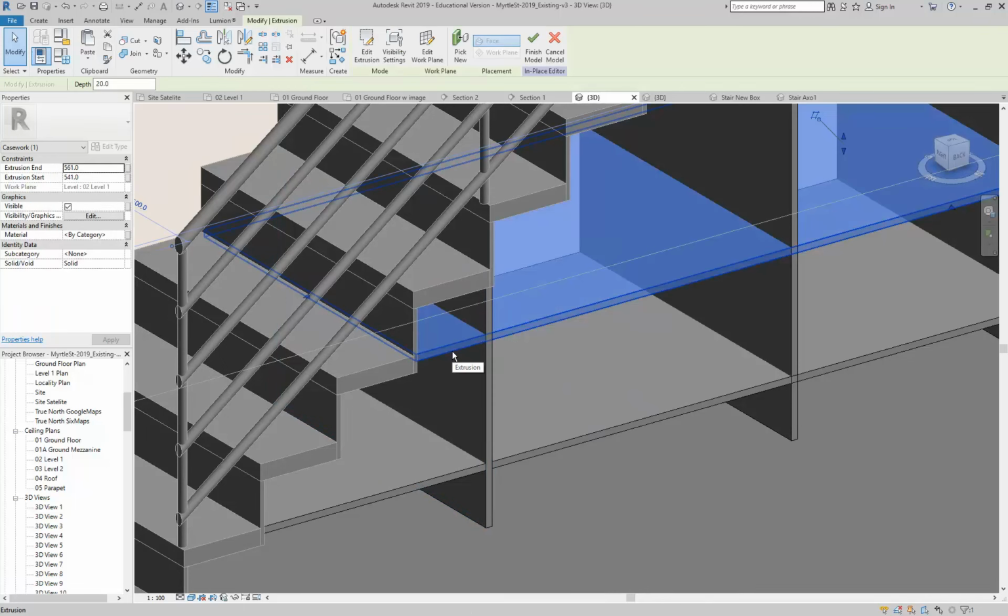You might not know if you don't need board thicknesses. It's not 20 or even 18. You make it the next one up. Normally, shelves, 25 is the basic rule of thumb. So yeah, 33 or so for bench tops, or 35 or 30, but yeah, 25 for shelves is good.